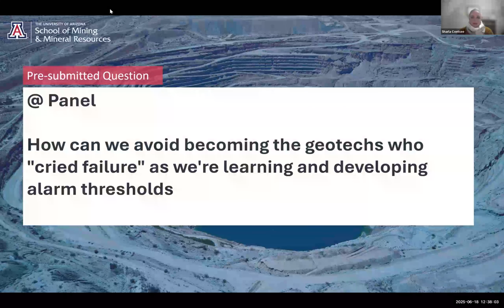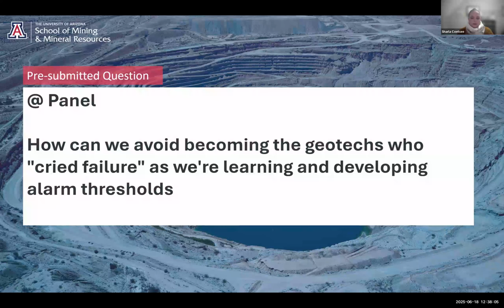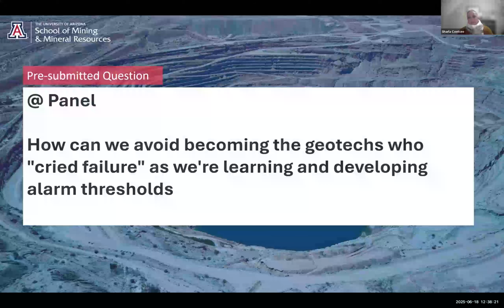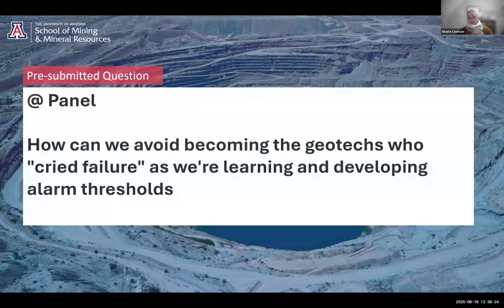And what I normally say in this instance, to build on what Ray's already discussed, is setting the expectations, explaining what you're doing. You're in a test phase. And typically, I wouldn't put on the critical alarms, for example, until I was really, really happy with the alarm thresholds, or set of alarm thresholds, below that level. So it's building up and understanding the data, setting the alarms, and understanding then the alarm thresholds that are applied and all the nuances that go with it.